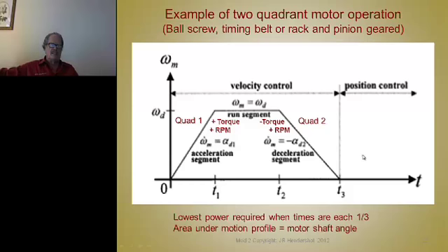It's interesting that diesel locomotives, they can't do that. When they decelerate or stop a train, the generators connected to the diesel engine, they generate a lot of power, but they can't put that back. They can't convert that back to diesel fuel. So they have to put big resistor banks on top of the locomotive to convert that energy to heat.